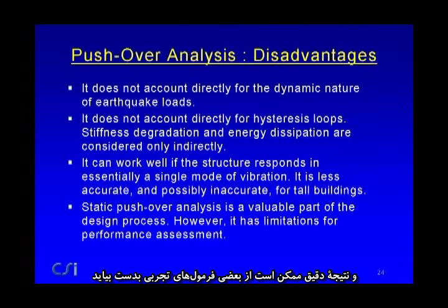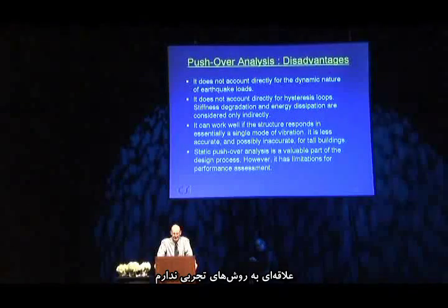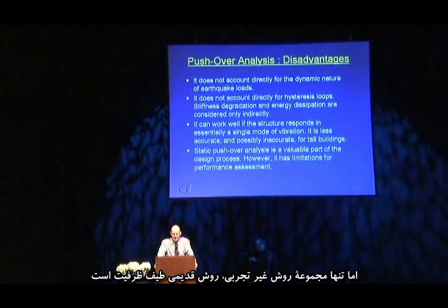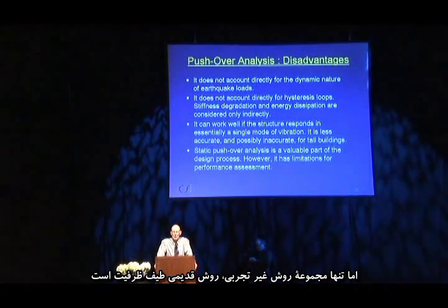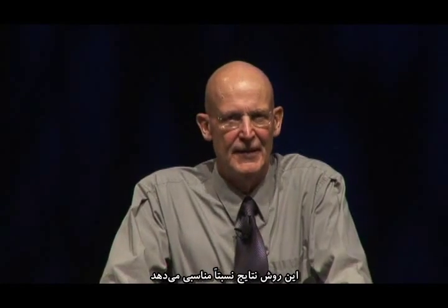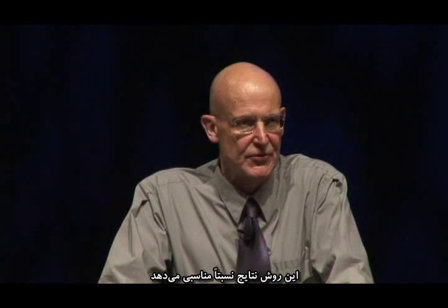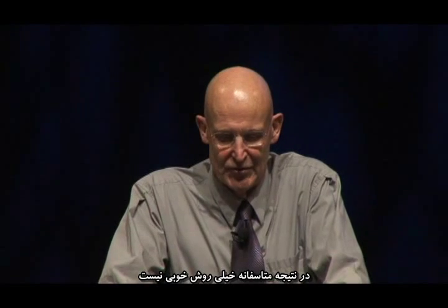It means it becomes rather an empirical method where people just run lots and lots of earthquakes past structures with a number of different hysteresis loop shapes, and massage the results and come up with some empirical formulas. And I don't like that sort of method personally very much. I've never liked empirical methods. But the only sort of non-empirical method is the old capacity spectrum method that tends to at least give the semblance of being a little more rational. Unfortunately, it's a very nice method conceptually, but it doesn't work very well in practice. And so, unfortunately, it's not a good method.